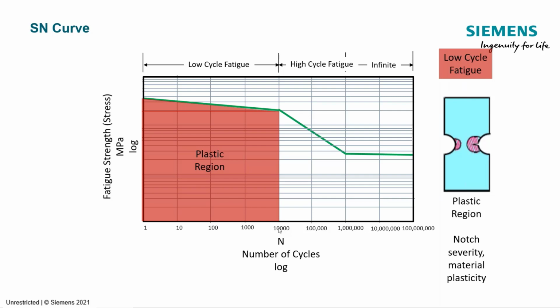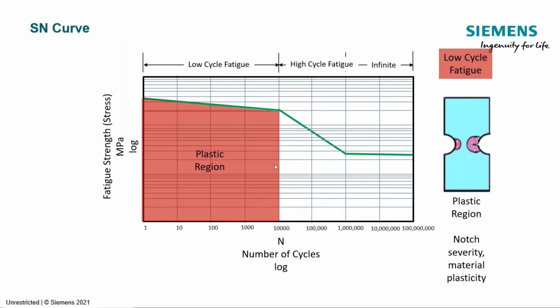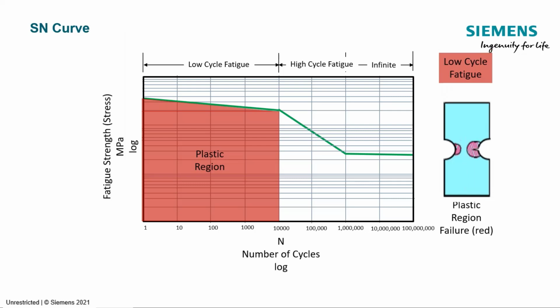And please take these numbers with a grain of salt. You may stop it at 1,000, 5,000. The other region may go, this one may go out to millions. Usually I see it could go a little above a million, but these are qualitative just to give you an idea. So this plastic region looks really big, but it's on a log scale. Nonlinear relationship between stress and strain.